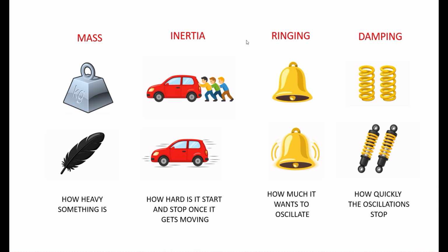A good example is shock absorbers in your car. They bounce up and down a couple of times, but without those shock absorbers, the car would bounce a lot more. So that is the term damping. Now, we use damping when we're doing sound treatment in a car. So, for example, putting butyl sheets on the door skin, inside the car door, to stop the panels resonating and vibrating, right? So that's damping.